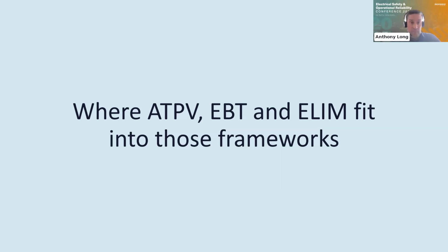Obviously we do a lot of matrices with customers and clients to make sure that they have a really simple, straightforward plan of how to layer up in certain circumstances to get the right protection they need, but working from a base layer which is practical for everybody. And when I say everybody, that is literally anyone who is at possible risk of arc flash, whether they're working directly or adjacent to live electrical equipment. They have a base level of PPE.